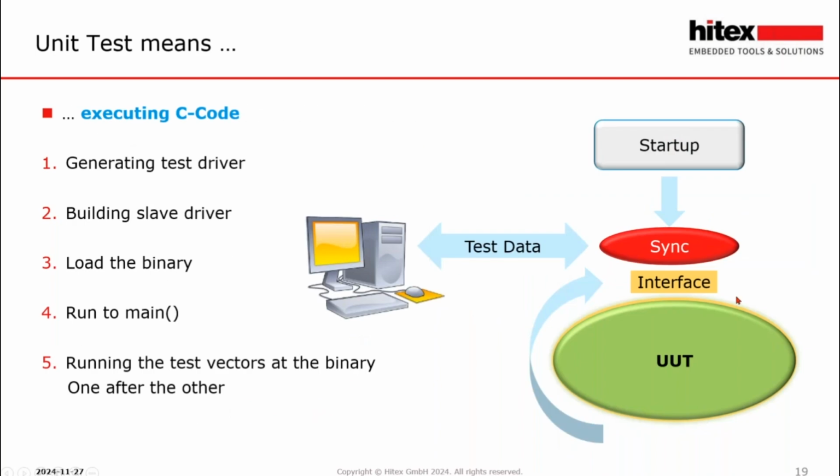That's very easy. Here we have to take care about the executable binary. We have this value in range, but for sure we need some startup code for the microcontroller, low level, and so on. TESSY will create C sources. So it's generating the test driver, and you can take a look at that. We have startup code, we have the instrumentation maybe. After that, you can imagine TESSY as a developer. After creating the C sources, the test driver, you will do the building. That means compiling, linking, and finally we get a binary.